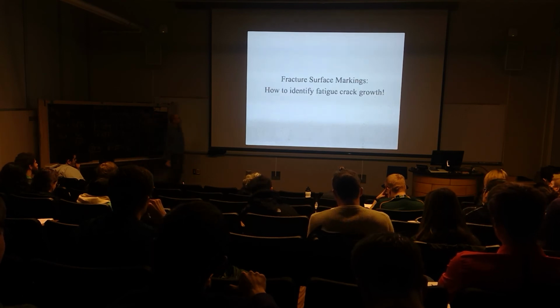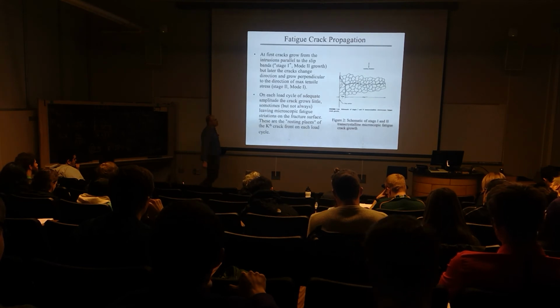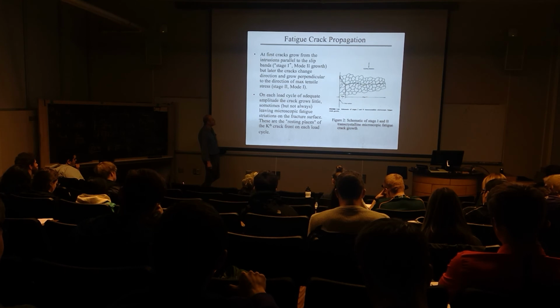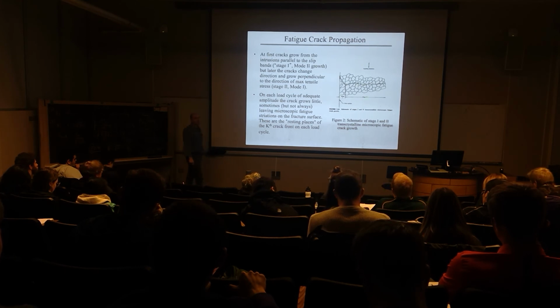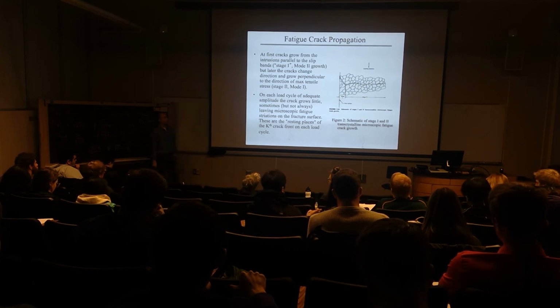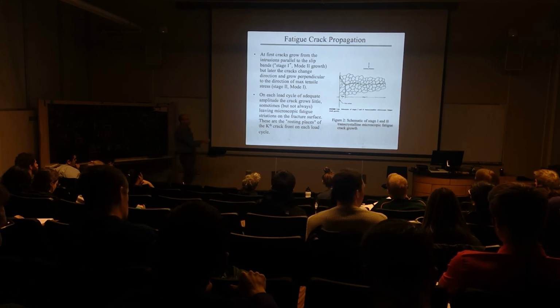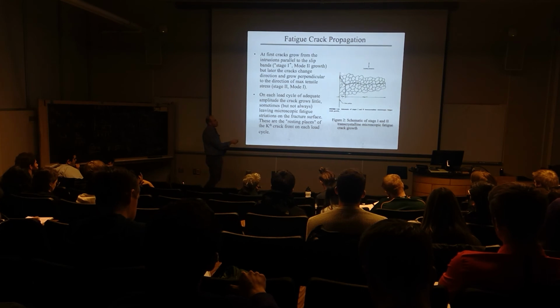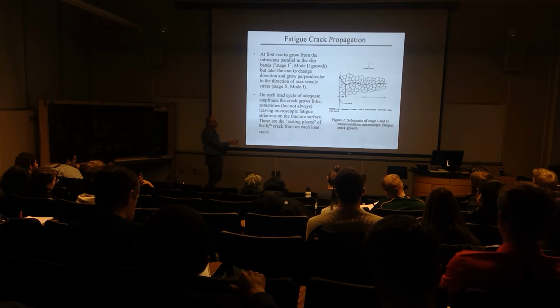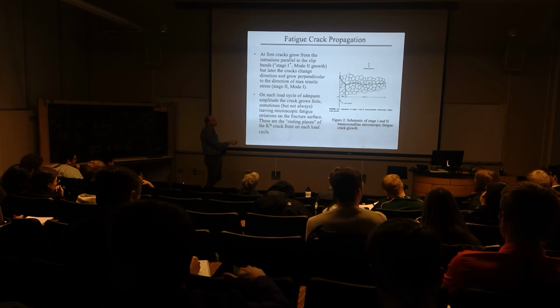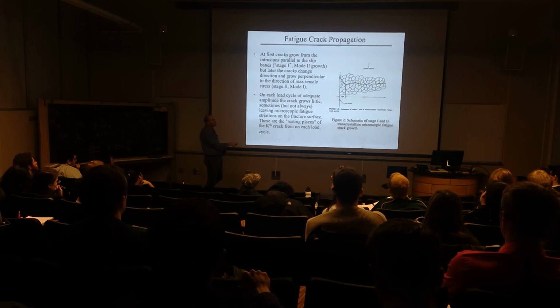Right? We're doing this because we want to actually use it for a fracture or failure analysis. And so what we want to do is think about the characteristics that that cyclic crack growth process will represent in the materials. Most cracks that start from the surface, if they don't start from cracks that are initiated by manufacturing, will start from slip bands, and these will extend over about 2 grain distances, maybe about 20 to 50 micrometers in distance, and then they'll transition to a mode 1 growth.